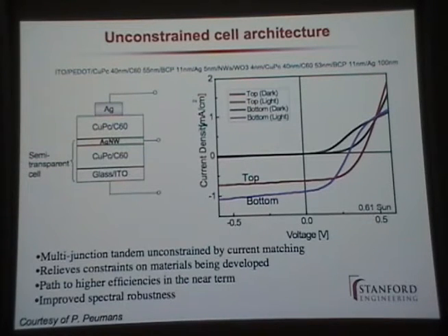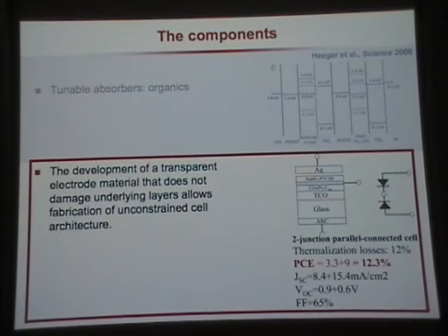And in 3-5, that's really determined by the fact that you can make transparent electrodes to carry the current through, but you cannot make them conductive enough to carry the current away laterally. If you were able to carry the current away laterally, then in each cell, you could put a terminal to get the current out, and you would get the current out from each terminal independently, so you don't have that current matching requirement anymore. And in that case, the efficiencies essentially add up. So each subcell has a certain efficiency, you just add them all up.